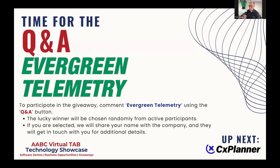We actually pull the old used sensor out and throw it away, and we put a brand new one in that's factory fresh. And then we do our NIST traceable calibration to that and send it back out. So that's an example of the type of drift that can occur in a particular type of sensor. But as Tony mentioned, modern day sensors for temperature and pressure don't drift. So basically, if they haven't been damaged, they're going to read correctly.